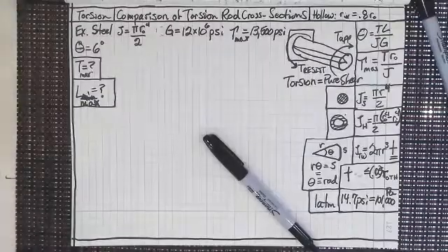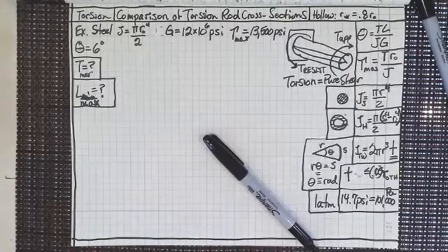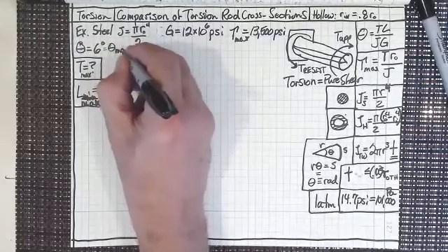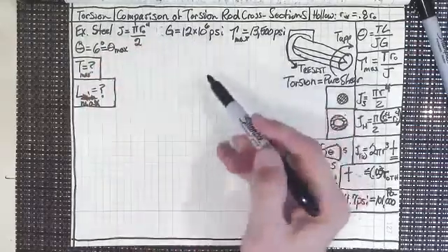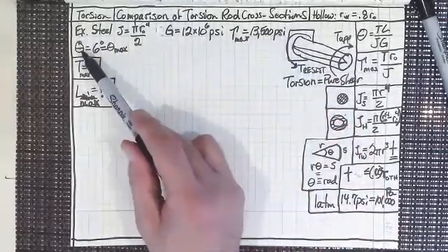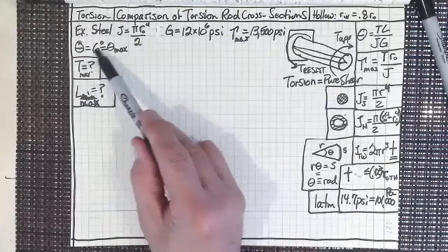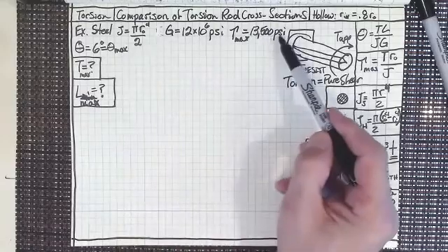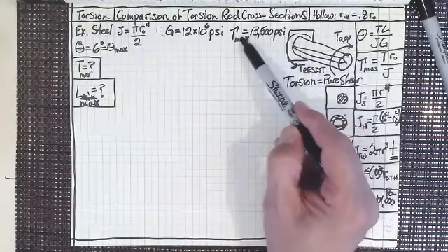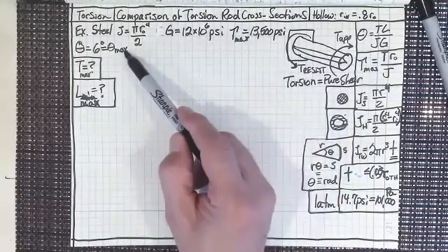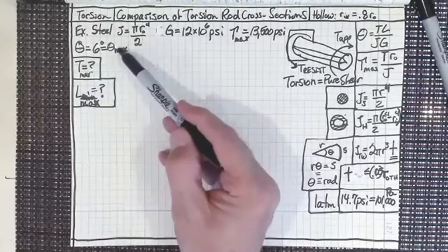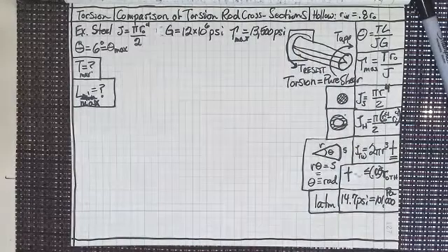No, I'm right. That is L max, and if I made L any longer, that would violate the maximum angle that I can go. This, of course, is the maximum angle of inclination right at failure. That's what I'm basically laying down as the line. I don't want this thing to move any more than 6 degrees. That's the maximum it's going to move when I apply the maximum shear stress to steel. I don't want this thing to go larger than 6 degrees. So this is the maximum. If I made this longer, that angle would actually go further, right?